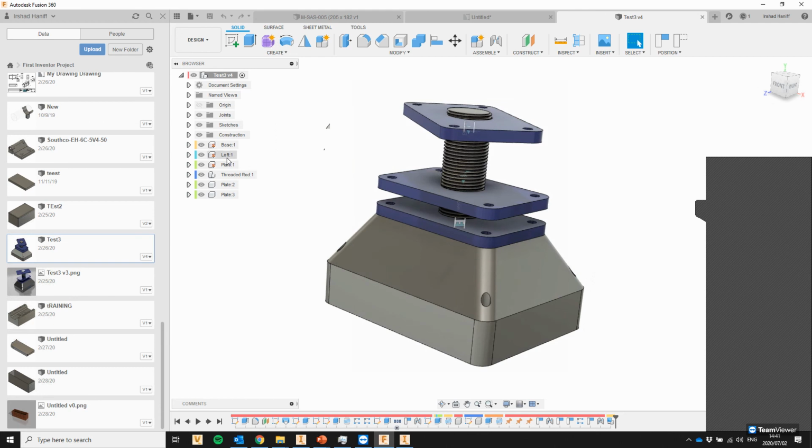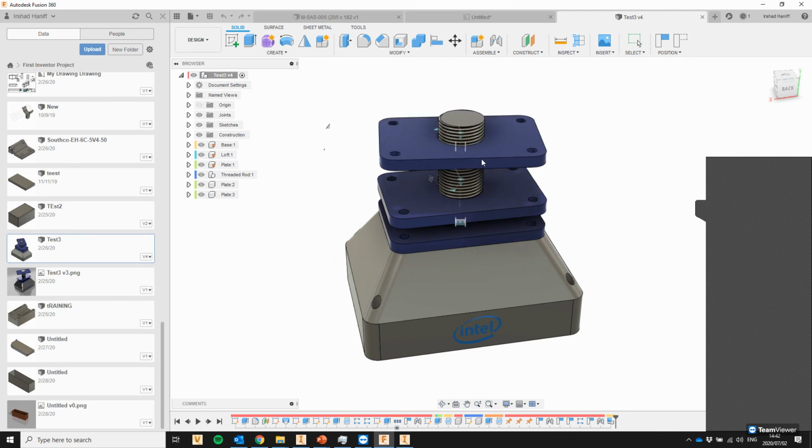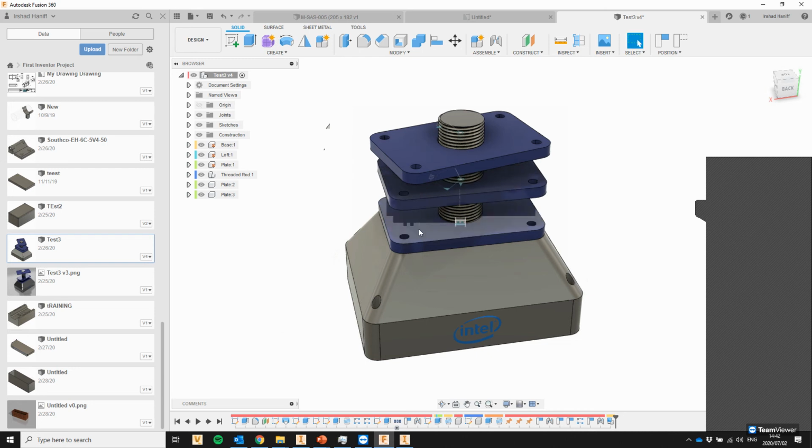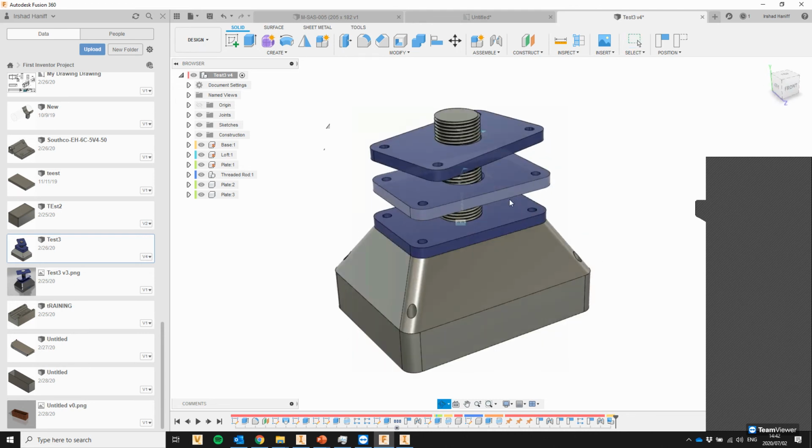So like we said, you'll notice that they have each separate component in the design, although it doesn't save it as a separate file. It's all one F3D file, Fusion 3D file. So no IPT and no IAM. And you can do sort of the same constraints and designs as you have in Inventor. So you can see that I've created some relationships between the two, revolving and aligned along the cylinder here. And those will let you create your drawing styles from there based on the position of these.